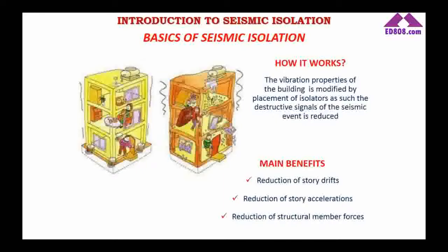How does it work? By doing that, we modify the vibration periods of our structure, and we try to prevent our building from the high frequency destructive vibrations coming from the ground.